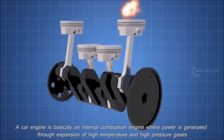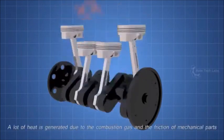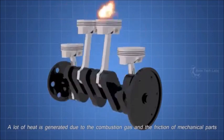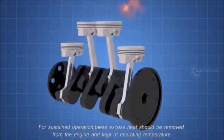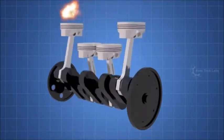It will turn on the radiator fan if the coolant on the radiator side is at high temperature. Now, the hot coolant in the radiator will release its heat to the atmosphere with the help of the fan. At the same time, the cold coolant received from the radiator will start to absorb the heat from the engine for the next cycle.